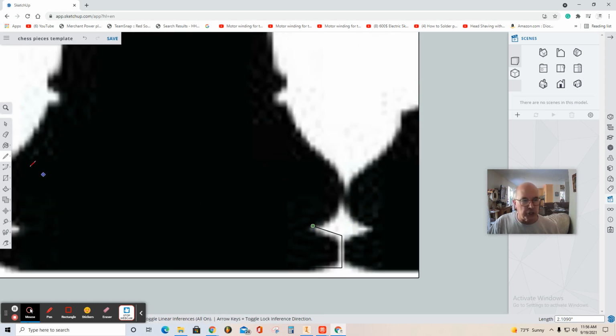And then I can interchange to the arc tool. So I select arc, it's a 2-point arc. Make sure things are green, endpoints are green, and you select and you pull. And you can just bear with me as I show you how to draw the profile here. And then I'll return to the line tool.